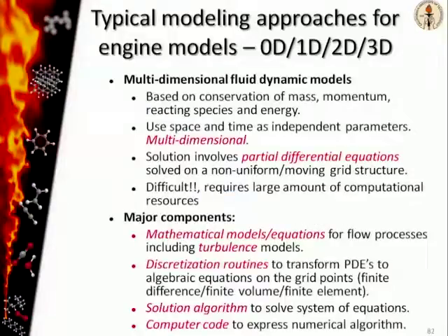Now, in the more detailed models, which involve multidimensional fluid dynamics, you actually solve all the fundamental equations, which involve the conservation of mass, momentum, reacting species, and energy. In this case, you have both space and time as independent parameters, and they're multidimensional. The solution involves partial differential equations, which are more difficult to solve and require a large amount of computational resources.